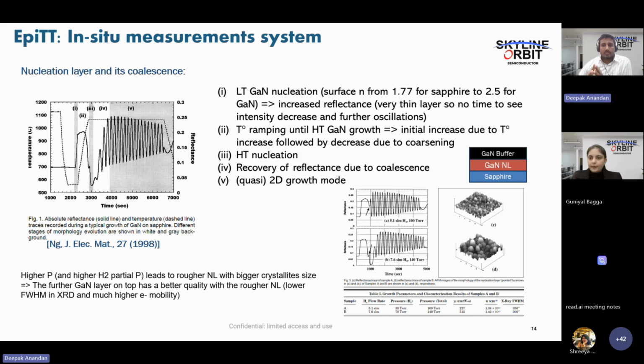So wafer thickness is based on the size of the wafer. For example, for 2-inch sapphire, we always use 430 micrometer. And if you go larger than that, like silicon, it will be around 375 micrometer. If you are going for silicon 111, it will be even thicker than 001. So typically in a gallium nitride system, we will not use 001. We will always use 111 to give the wurtzite structure.